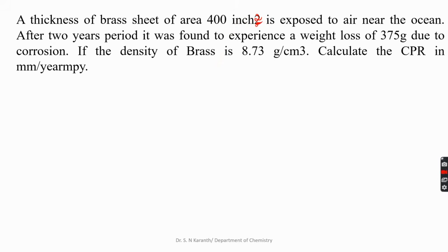near the ocean. After 2 years period, it was found to experience a weight loss of 375 grams due to corrosion. If the density of brass is 8.73 gram per cm cube, calculate the CPR in Mmpy, and in terms of Mpy.